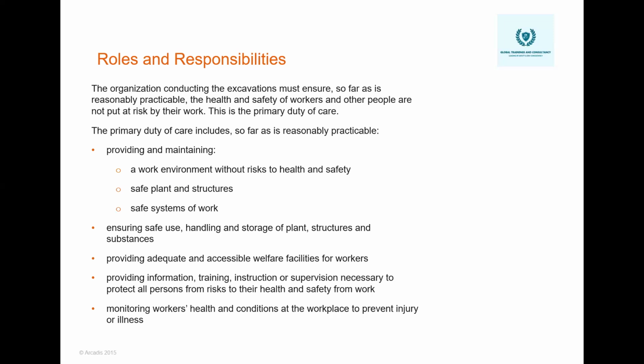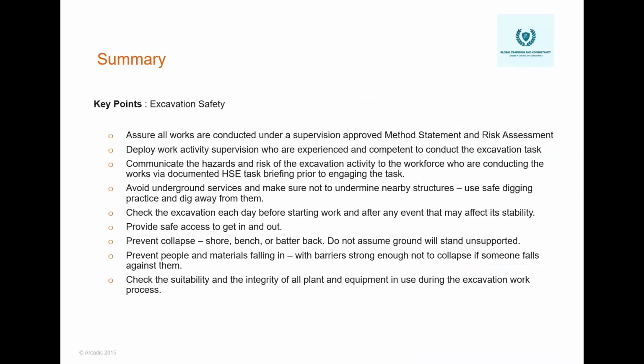So we have to ensure that the permit to work is implemented. A valid work permit is available, and appropriate supervision is available, like a supervisor who has experience in that kind of job and is available to monitor the activities. The plants and equipment which we are using are inspected and safe, with no leakage or damage to the equipment. These are responsibilities.